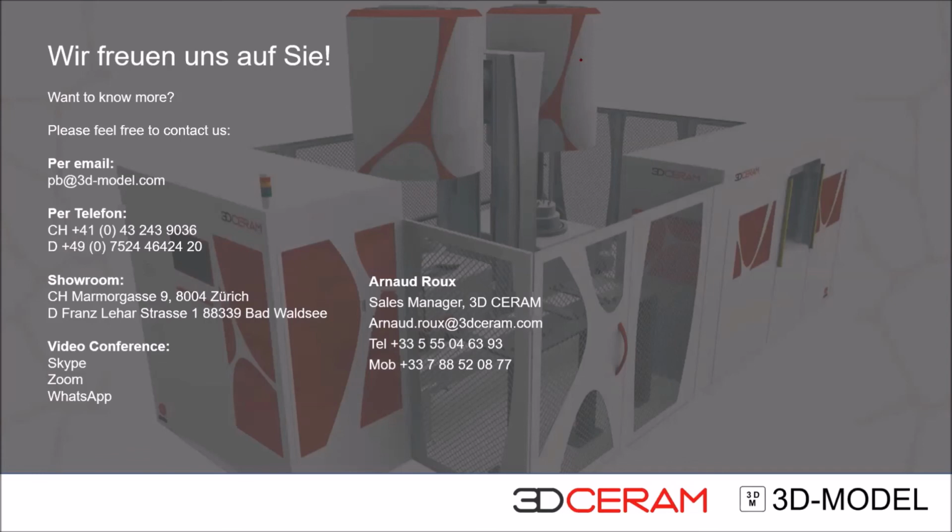And because of the paste, the slurry we are using, the part won't move on the support. So when we remove all the unpolymerized paste, it's easy to remove the support from the part. And as I said, we will reuse this support for debinding and sintering. So the support is also made of technical ceramics.